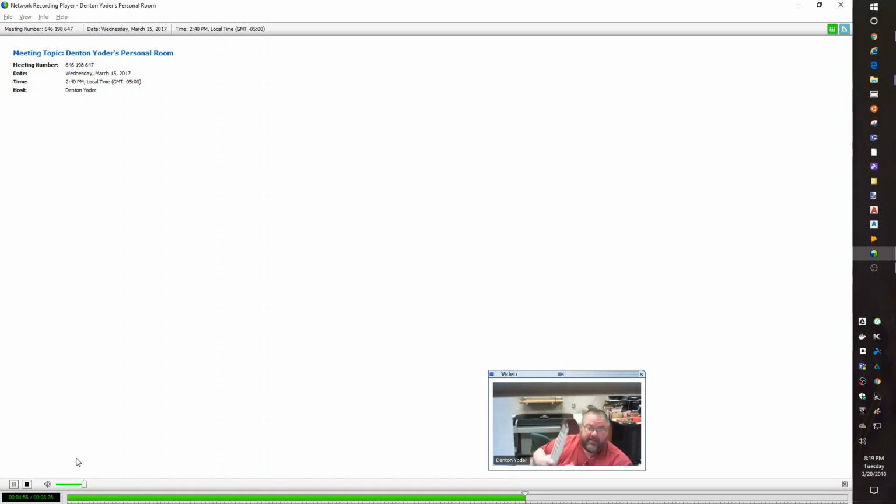You will raise the pole slowly while it's in an upright position, listening for the beep. You will get a beep pattern whenever it encounters the laser. There will be one beep for too high, another beep for too low, and pretty much a steady beep in the middle. So you continuously raise it until you hear the beep. Then right at the line, you record the distance as your measurement. Once it reaches the extent of one pole, it will click, and then you're raising the second pole.